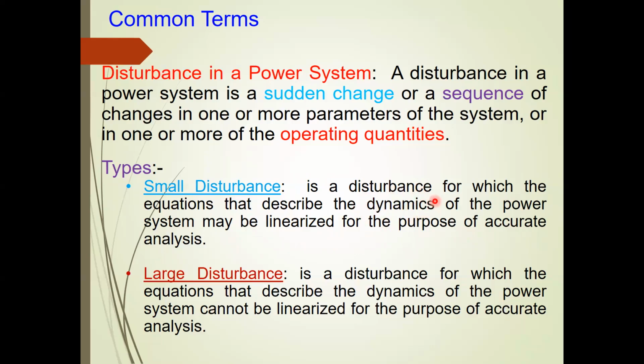No perturbation. But if I say there is a small amount of change, let's say 1%, 2%, 3%, 4%, or 5%. Let's say your generator was 500 MVA and your load demand was also 500 MVA. So this is a perfect match, a steady state operating condition, perfect equilibrium. Now let us assume there is a change in the load by 10 MVA. The initial operating condition was 500 MVA, right? Now 10 MVA, if you take the percentage out of 500 MVA, how much percentage is it?